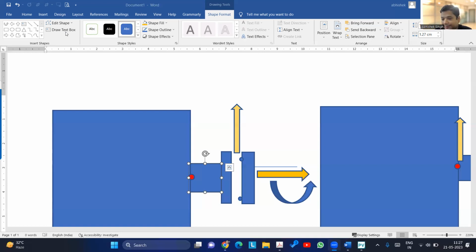See, a STAMP job does not mean that any requirement has changed. Requirements are the same, but they try to follow each and everything. They don't ignore. With normal jobs, we try to ignore. Okay, some external loads are coming on the flange. It's a standard flange, just leave it. Nozzle neck, we don't bother. But if you are actually doing the design and you understand this principle, it does not matter whether it is stamp or not.